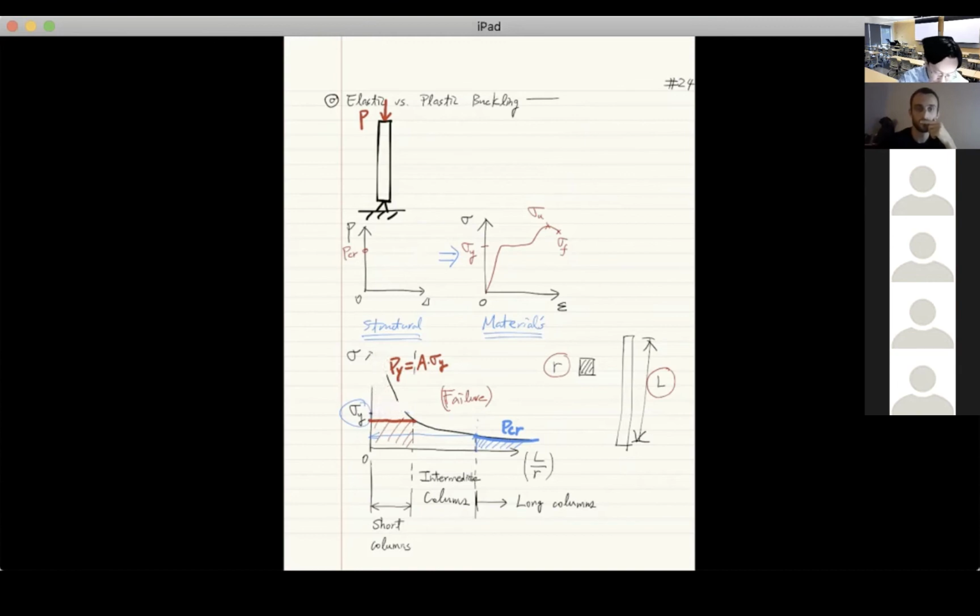Even so, the theoretical curve will predict it, because the theoretical curve is just math. Mathematically, you can put it in there. But material-wise, material cannot go above that. So the actual design curve people use is to use the material's capacity. In this case, starting with sigma y, you just decay it and go down like this.